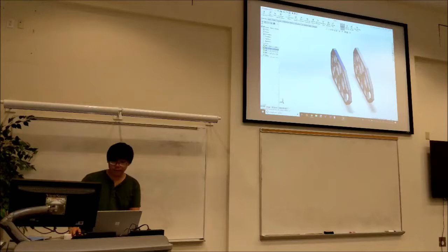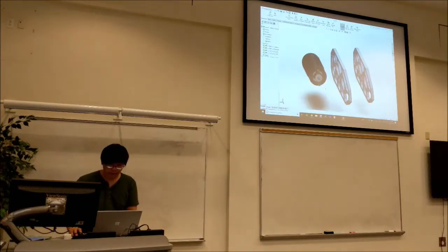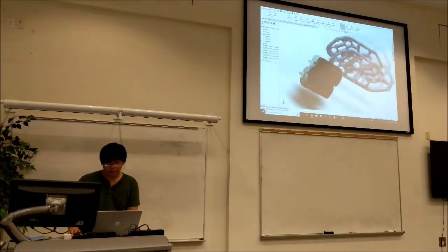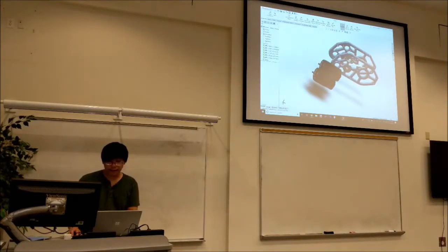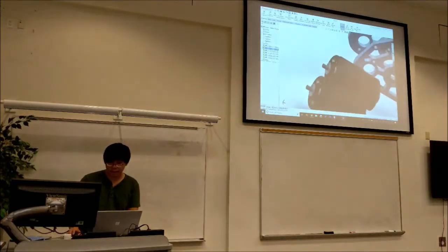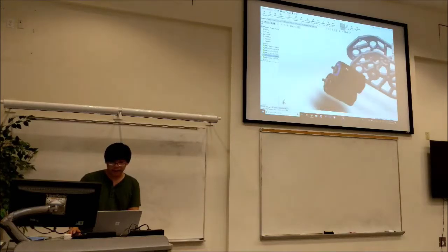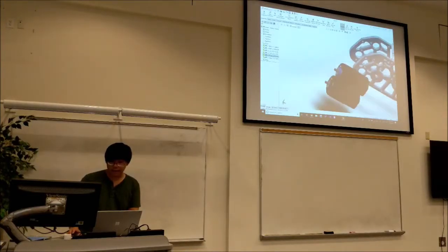And now, because we have this design library, we can just pull in a 775 Pro, actually 2 of them. And remember how we designed this plate? This is where the motor fits in, and we put this hole in because this motor has this kind of protrusion out the front. So now if we make this concentric to this hole,